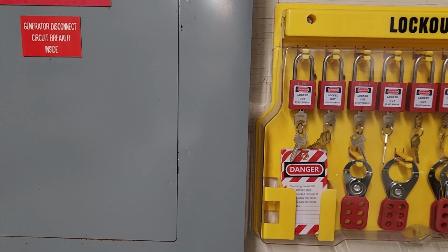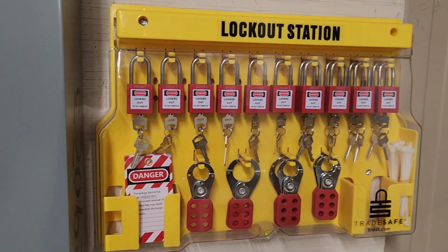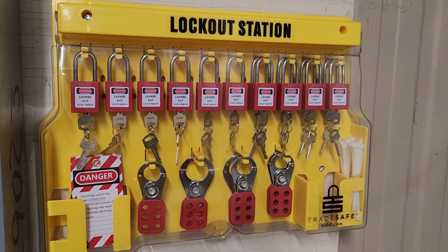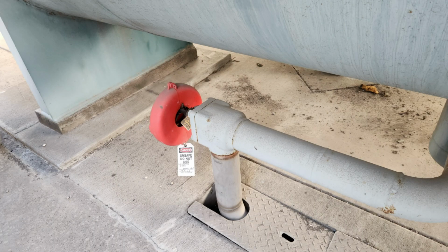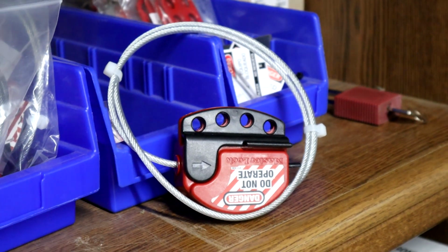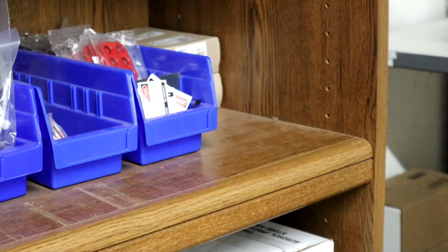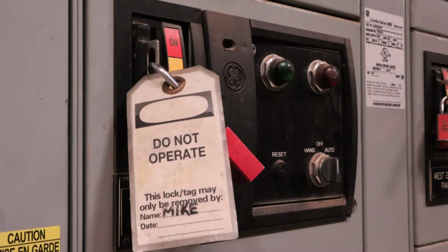Lockout-tagout, which is also referred to as LOTO, is a critical safety procedure that protects personnel from accidental equipment startup or the unexpected release of hazardous energy during service or maintenance. The main goal of LOTO is to ensure that all energy sources, including electrical, mechanical, hydraulic, pneumatic, and stored refrigerant pressure, are completely isolated before any work begins. This prevents injury from moving parts, electrical shock, refrigerant release, or sudden system activation.